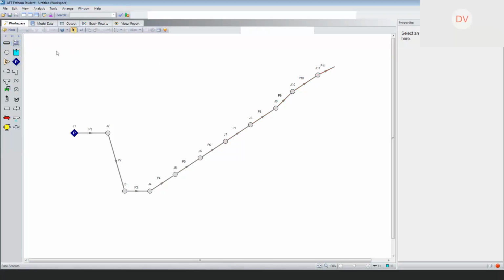Okay, I'll have one more of those. And then the final will not be a branch, it will be an actual other assigned pressure. That assigned pressure is what we're targeting to have the 50 psi to be able to place the water into the reservoir. If your actual pressure ends up being lower than that, your model will end up showing that there's an error.